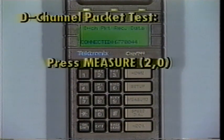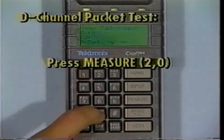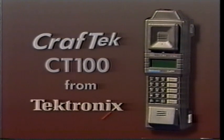You can further test the D-channel capabilities by sending the quick brown fox message. Go to the D-channel packet screen by pressing Measure 2 0. Press the 1 key to start the transmission of the fox message. The display will show you the message being sent out, and it will also display the message that is coming back. This will verify that the line is provisioned for D-channel packet and that the packets are being transmitted through the system properly.